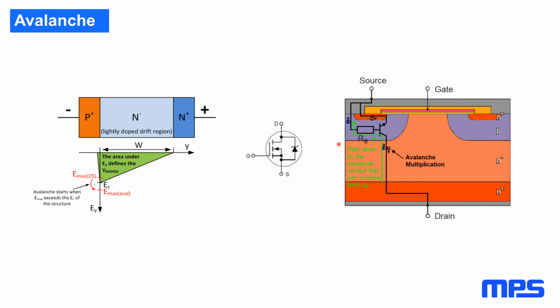What is the calculation of gate resistance? I'm not sure if that refers to the actual gate resistance of the device, which is generally, I don't think, shown on a data sheet, so I don't know where you would get that. Or if he's referring to series resistance into the gate. The series resistance, you can calculate largely based on the amount of time.